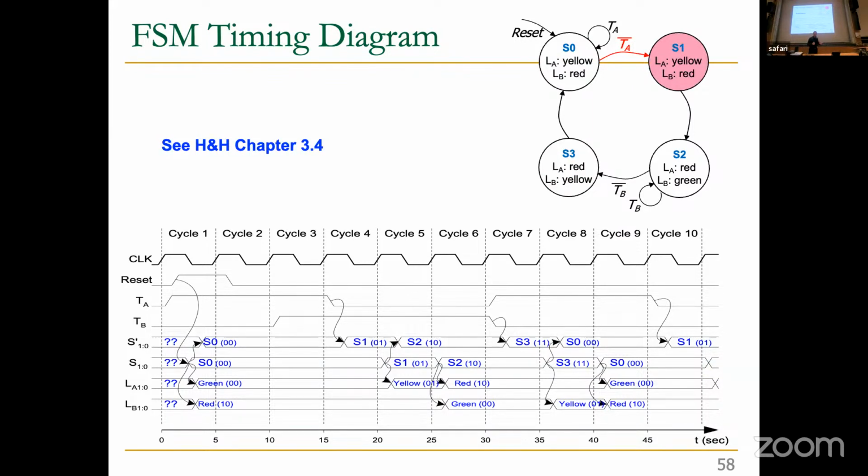So this means that if you want this to work correctly, your clock cycle should be long enough to accommodate the delay of the combinational logic and the latching that we have, right? This is really critical. If your clock cycle is so short that the combinational logic takes longer to settle, to evaluate its outputs from the time inputs change, then you will not get a properly working system. That's the importance of timing. Your clock cycle should be long enough to accommodate the longest combinational logic delay that you have in your system. And we've actually seen that combinational logic. So let's go back.